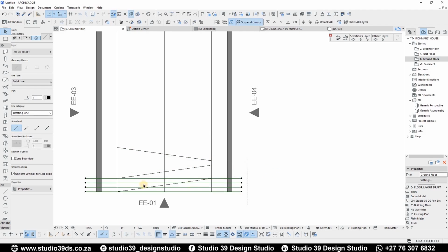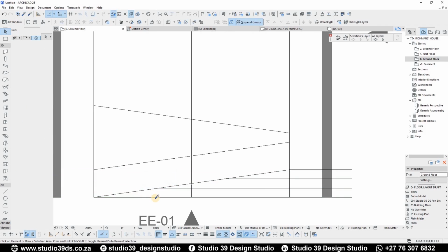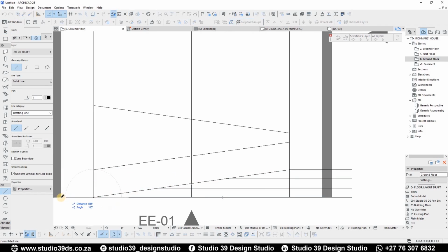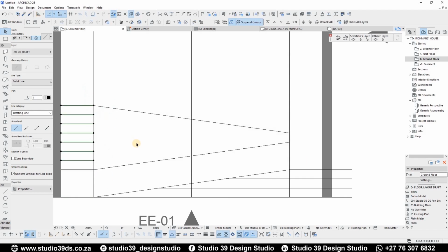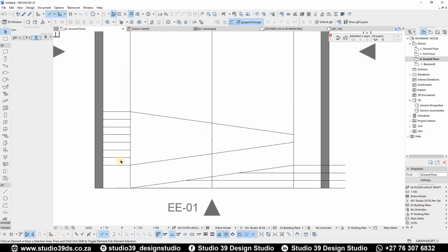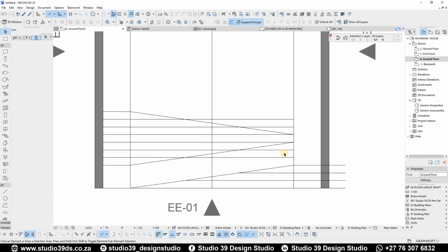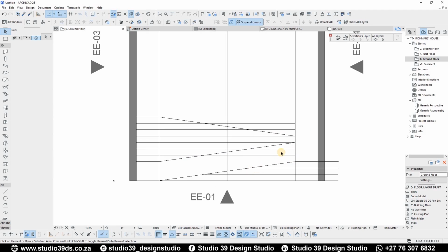Now you can go ahead and trim the first set of treads and define the starting landing and create the next set of treads as indicated using the previous multiply method. Extend the new treads to the other side of the stairway. Trim them by holding down the Ctrl key.